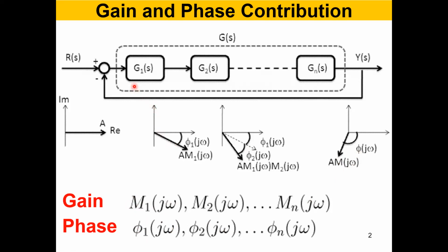Okay. So for example, if you send a signal of, let's say, 1 radian per second through this block, let's say it attenuates by a factor of 0.9. Okay. So a 10% drop in magnitude. Then you send a 10 radians per second signal, right? It will not attenuate by the same factor, 0.9. It will have a different factor. So that's what you need to understand. M is frequency dependent. Okay.